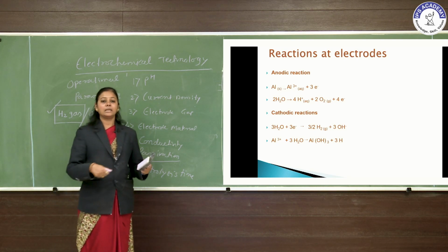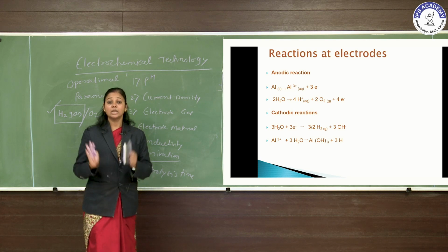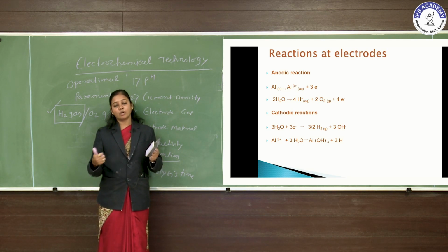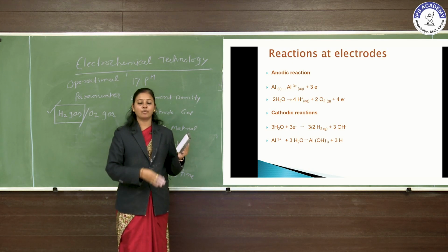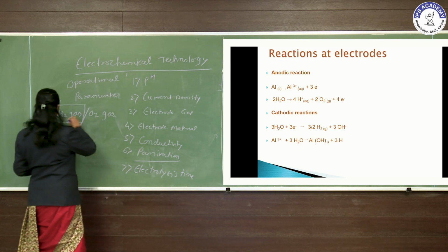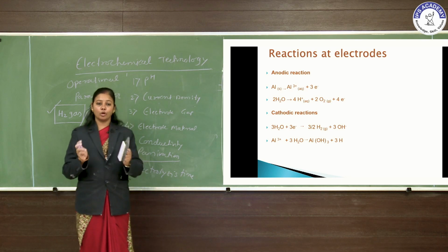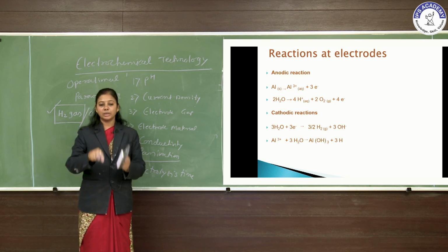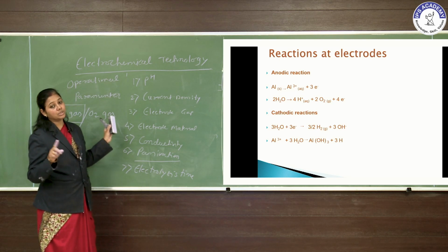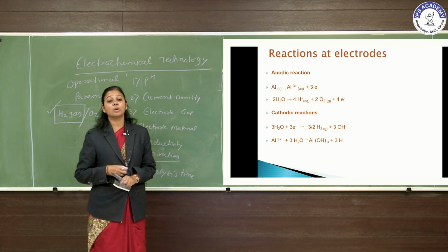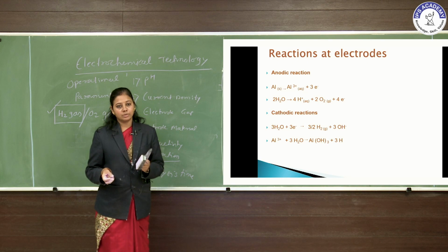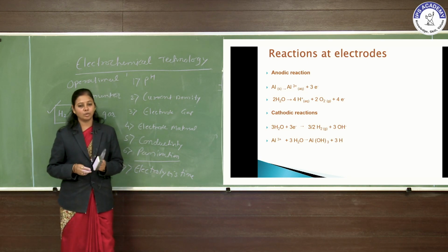You can do the electrochemical treatment on textile industry wastewater in small scale textile units. They can use this electrocoagulation technique, and ultimately they can reuse the treated water in the system or for power generation. And during this electrocoagulation process, if there is a generation of hydrogen gas, you can measure the volume of hydrogen generated, store it, and use it in the system or as a fuel, because storage and transportation of hydrogen gas is very difficult.